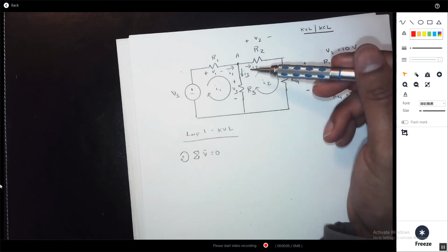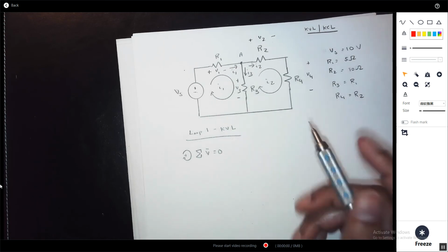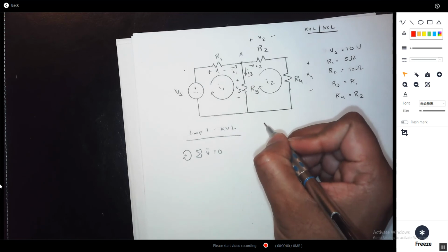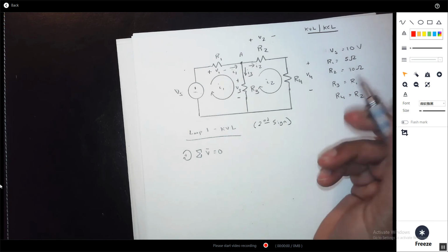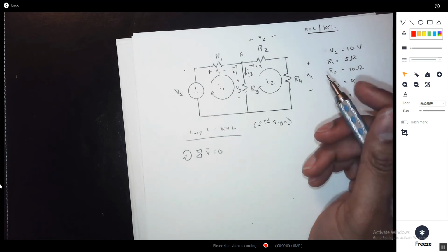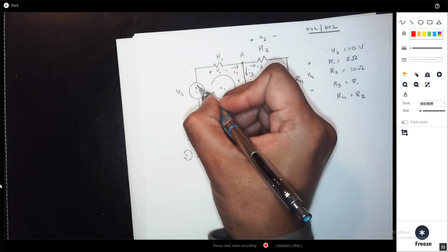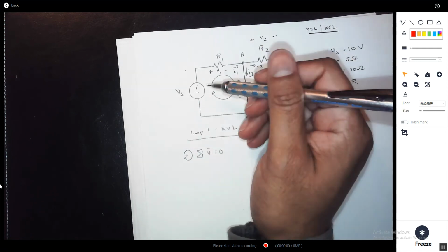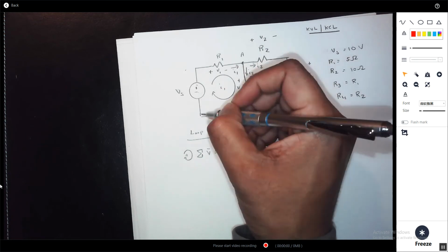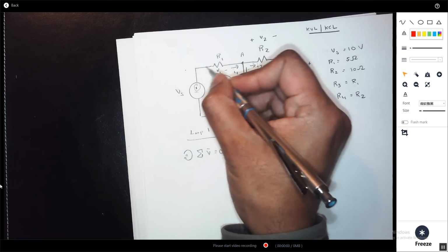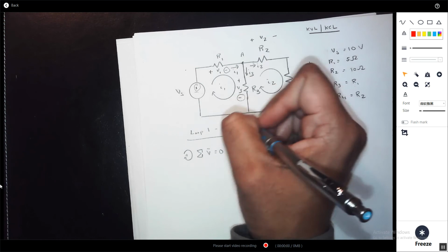The dominating current, I3, on KCL is going to drop here. Okay? So based on that, we're going to use sign convention. Use the first sign or second sign. Now I'm going to use the second sign. Okay? You can use the first sign. You'll still get the same answer. Okay? So what we're going to do is we're going to circle as the current travels. So I generally start from here, for the simplest node first, simplest component first. So I go up here, say, okay, it's the second sign, and I come back around the loop, second sign. This is my voltage loop here, okay?